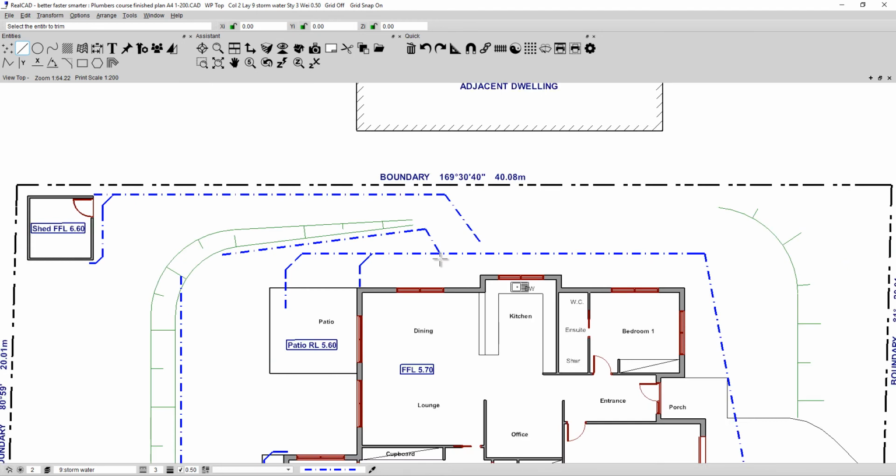Not that it really needs to be, and I've got the trim command still active from using it here. It's still active. I can use this one and trim it down, because making something longer or extending it and shortening it is still called trim. Click here, and I now know that that one's joined to where it should be as well.